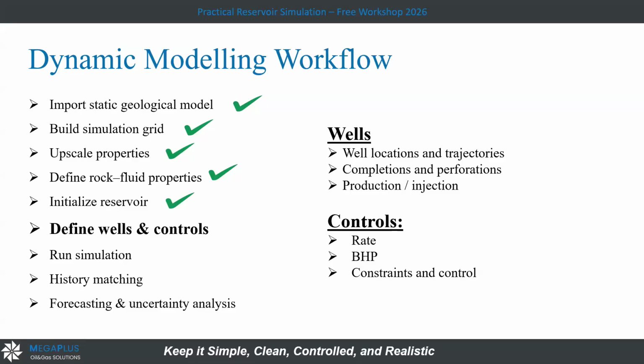And here, before we go through this workflow, in the initialization milestone step, when the static model is finished, we agreed yesterday that I have an output of volumetrics. I have the volume. After I made the initialization, putting in the dynamic model the capillary pressure, the relative permeability, the datum, the pressure, and the saturation distribution, all of this will give me a volume according to the curves and the new data that I insert.